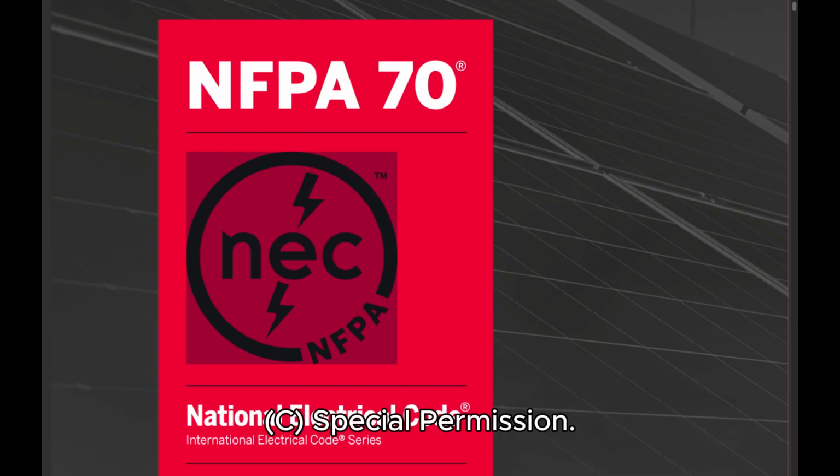C. Special Permission. The authority having jurisdiction for enforcing this code may grant exception for the installation of conductors and equipment that are not under the exclusive control of the electric utilities and are used to connect the electric utility supply system to the service conductors of the premises served, provided such installations are outside a building or structure or terminate inside at a readily accessible location nearest the point of entrance of the service conductors.